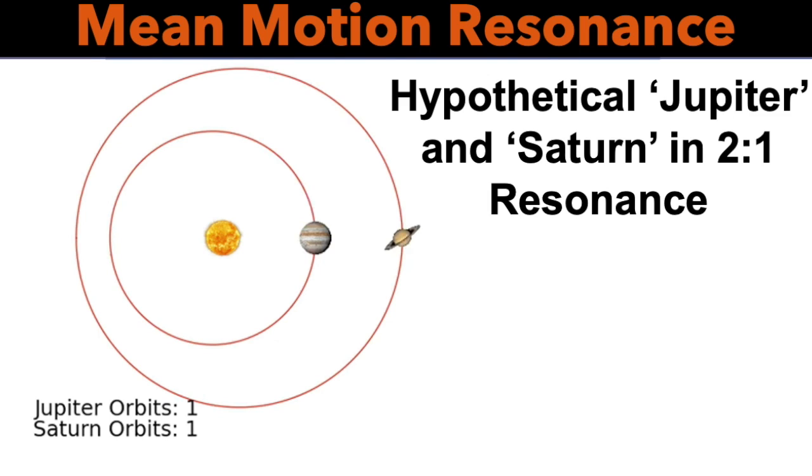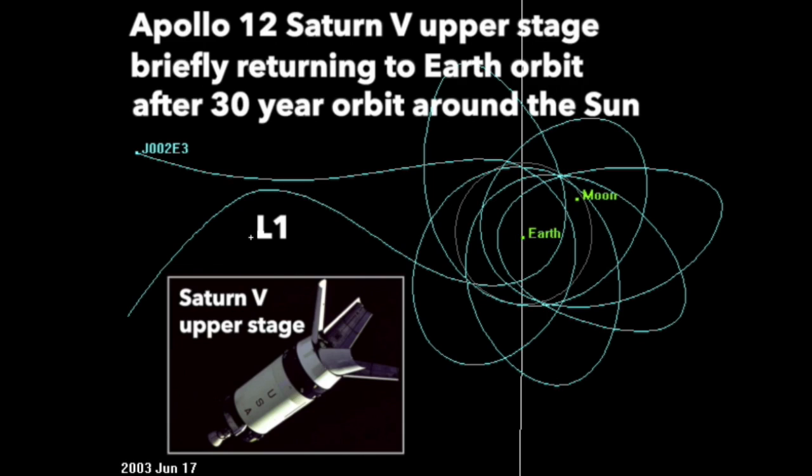All right. But when you're designing those trajectories, if you want to go from a halo orbit around the moon to the heliocentric, are you just patching together the circular three-body equations, finding conditions where the final condition here meets the initial condition there? Yeah. And then when we put that in a more realistic model, it seems to do pretty well. You can use differential correction again there to get something more accurate.